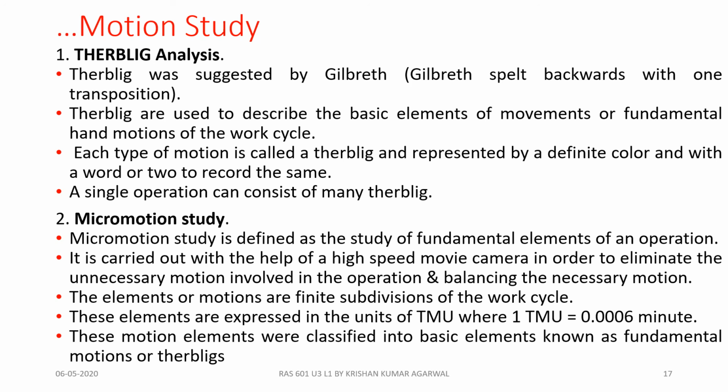The next type of study considered under motion study is micro motion study, which can be defined as the study of fundamental elements of an operation, carried out with the help of a high-speed movie camera in order to eliminate the unnecessary movement involved in the operation and balance the necessary movement.